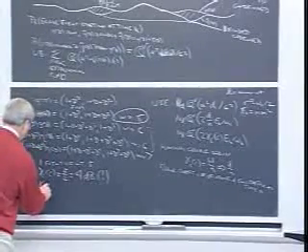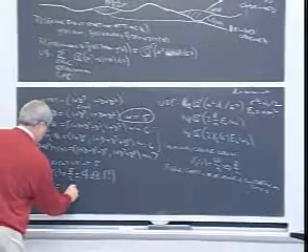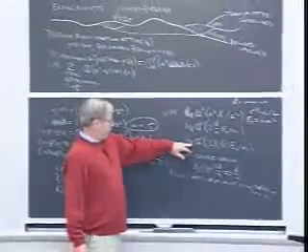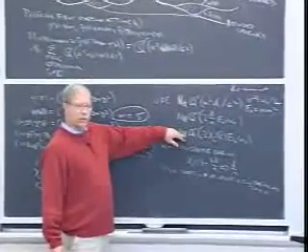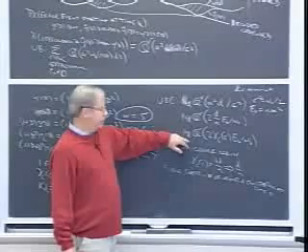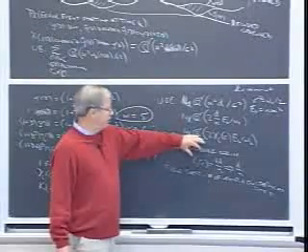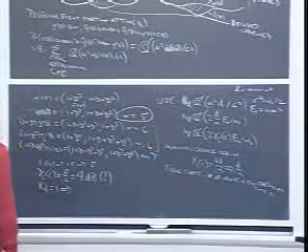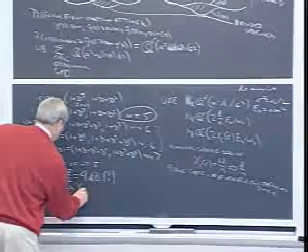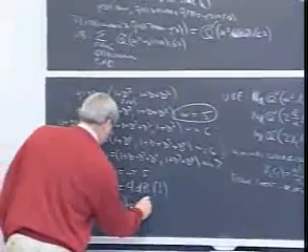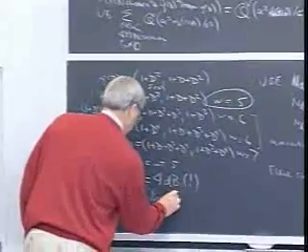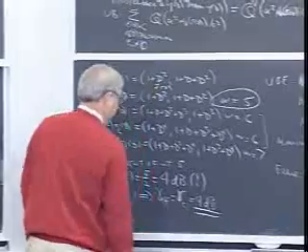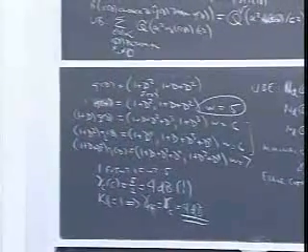And what is Kd equals 1? That implies, again, we have the same argument about whatever the error coefficient is. You could plot this curve. The larger the error coefficient is, the more the curve moves up and therefore over. You get an effective coding gain, which is less. But this means, since it's 1, you don't have to do that. The effective coding gain is the same as the nominal coding gain. It's still 4 dB. So it's a real 4 dB of coding gain for this simple little 4-state code.